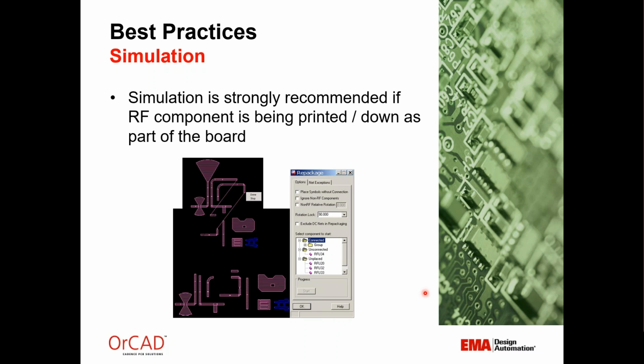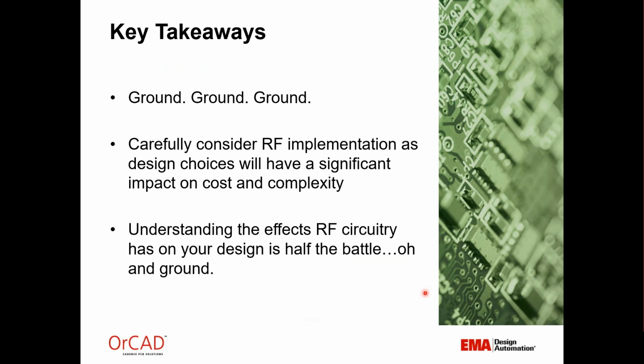Simulation is strongly recommended. If RF components are being printed down as part of that board, simulation should be a requirement. Any serious RF design should be simulated. We interface with those simulations with IDF files and DXF files. We do not simulate, but we interface with those simulation tools. The key takeaways here: ground, ground, ground. I cannot say it enough, ground.